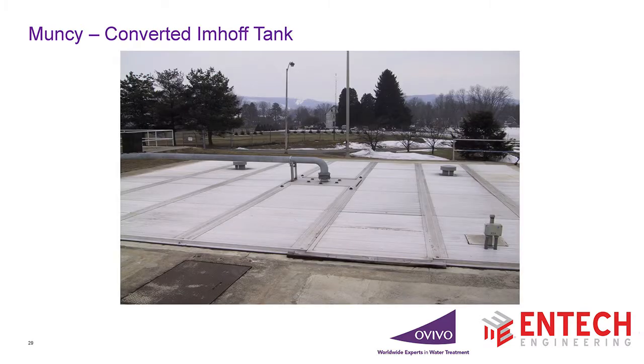And this is the Imhoff tank with the cover on it. It was a square tank. Those of you familiar with Imhoff tanks, we took out all those internal baffles, and we put a draft tube aerator in the center. Draft tubes work well on deep circular tanks or deep square tanks. When you start getting rectangular, it's better to shift to a shear tube type of diffuser, and we'll see some of them.